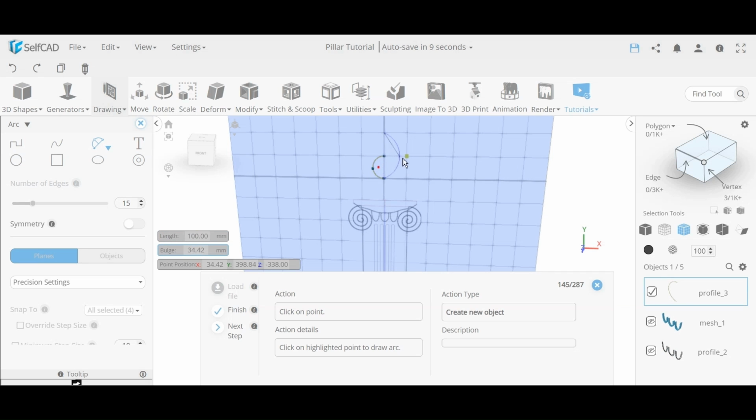And now I'm doing the same thing over here, where it's snapping. And this is actually very interesting, how we draw a spline. A spline is half arcs connecting to another half arc, which gets bigger in size, and then another half arc which gets bigger. And we use the grid vertices to allow me to draw them with precision as it gets bigger. So you see the first thing is we snapped a 25, and then we made it snap to this, which is basically another, I guess that's 50. And then we're going to do over here, let's see, snap here, and then we're going to enter 75.